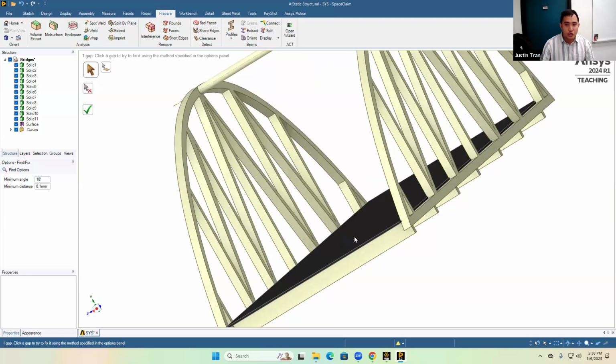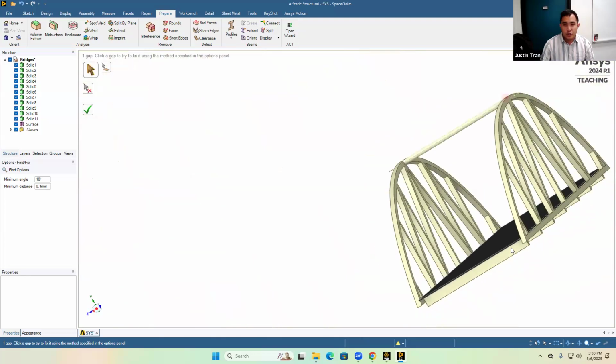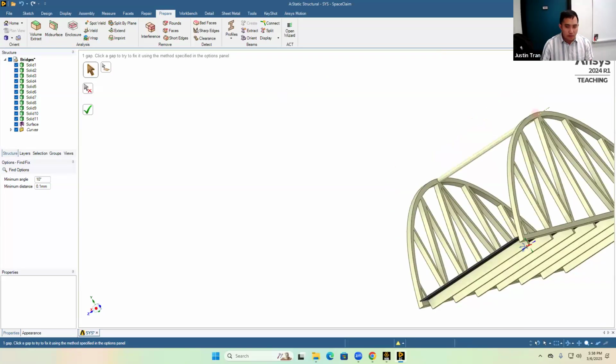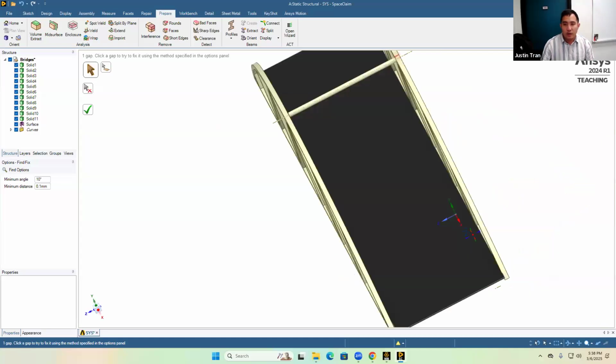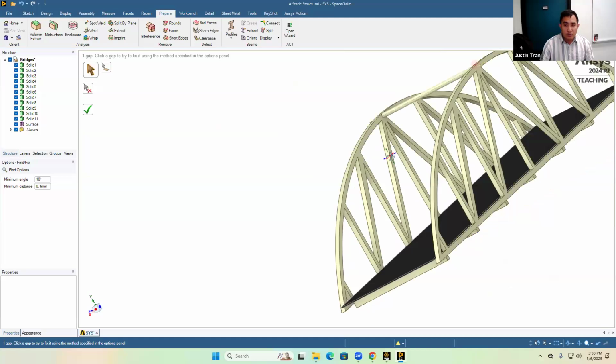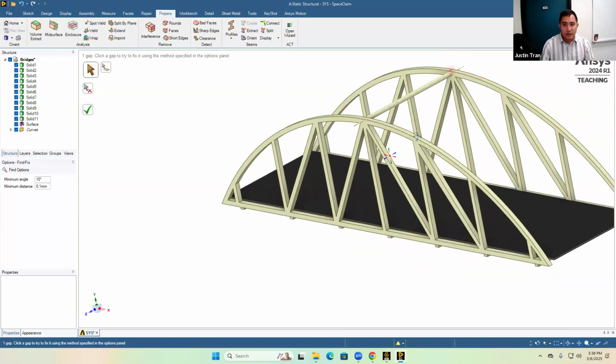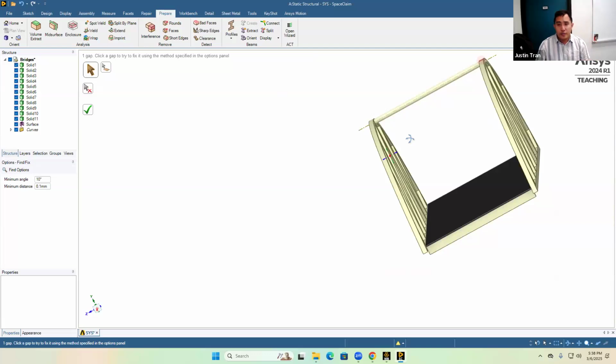In fact, it almost looks like a shell already. Okay. Very thin geometry. We have all of these supporting beams, which are literally beam-like geometries, so we can convert those to beams as well. And then the sides of the bridge, since these are both parallel, thin structures, we're going to convert these into shells.